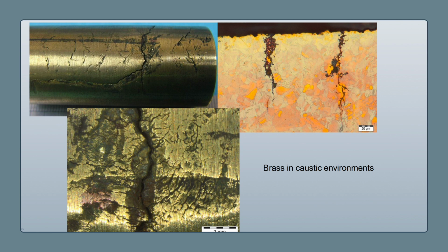So stress corrosion cracking has this branchy cracked nature on the cross-section of the steel. On the lower image to the left-hand side, you can actually see the pinkening of the yellow brass where you see some dezincification. That's so interesting that actually you can physically see a change in the color, sort of evidence of the fact that there is a problem. Yeah, that's quite distinct with copper alloys. You can actually see within the branch cracking, dezincification within the alloy. There, that pink is far more obvious. Yes, again, copper is one of the examples I like because you can instantly see the difference. With some other materials, you won't so easily see that de-alloying change.